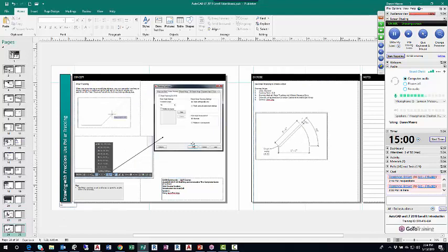We'll use the line command, absolute Cartesian coordinate 0,0, direct distance entry, and polar tracking to create the door shape that's on page 24. So I'm going to click on the little graphic on the page here. There's not a ton of information here, but I'll copy it and paste it into the new drawing I'm about to start.